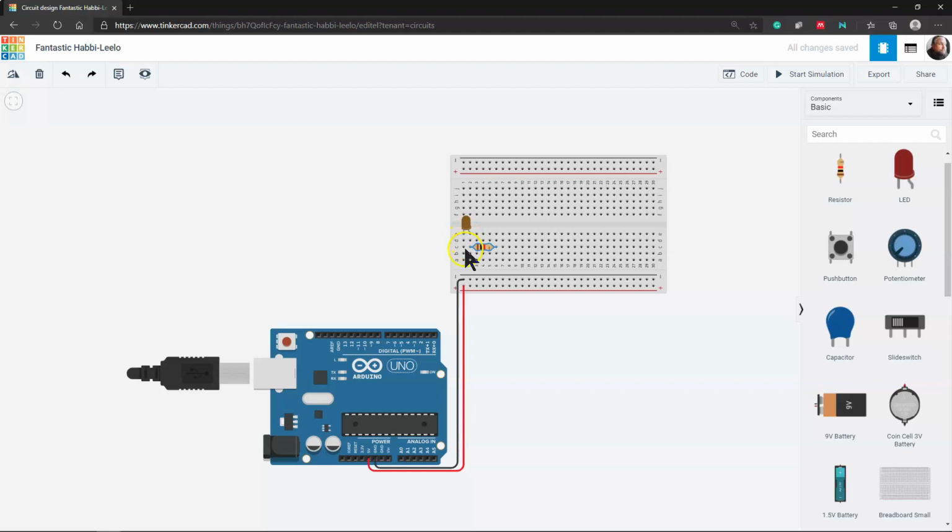So from here, again, the cathode needs to go to negative. So I'll just draw a line, get it down to here, and I'll change that to black, just to make it easier that it's still following from here being negative. And then next, anywhere on this row, we need to connect the positive, because again, this is going up and through the anode. So here, down to the actual positive, and again, just being red, just to make it clear that when I'm pulling stuff from the rail right here that has the negative, ground, it's going up, and here's the positive.